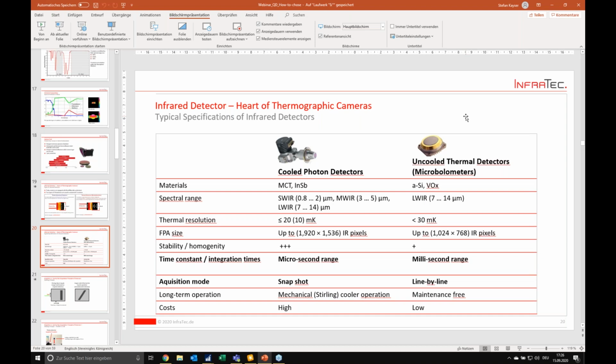Then this will simply overpower the performance of your camera and make all the efforts on the camera and the calibration process of this camera useless, because the whole measurement chain will overpower this. So the crucial point in contactless temperature measurement is the emissivity of your parts itself. You have to consider this first, before thinking about absolute measurement accuracy.